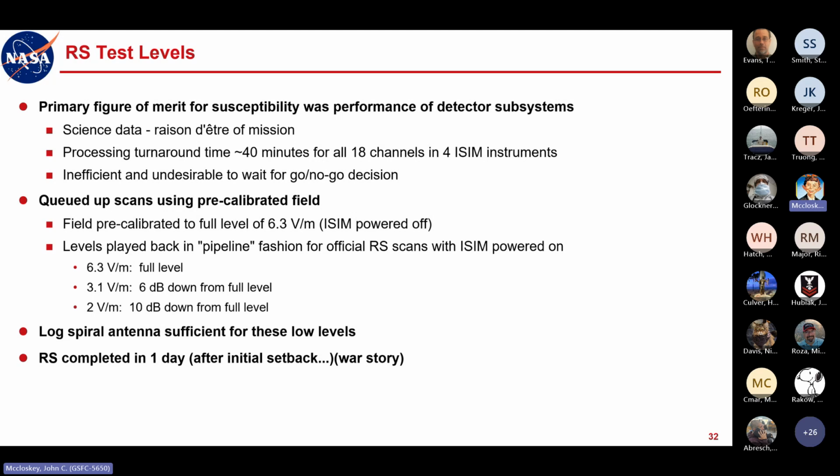We're applying that 1 kilohertz pulse modulated signal, so it should be on for 500 microseconds and off for 500 microseconds. So about 50 pixels should see the applied signal and 50 pixels would not. So you should see the striping pattern if the modulation signal was applied.